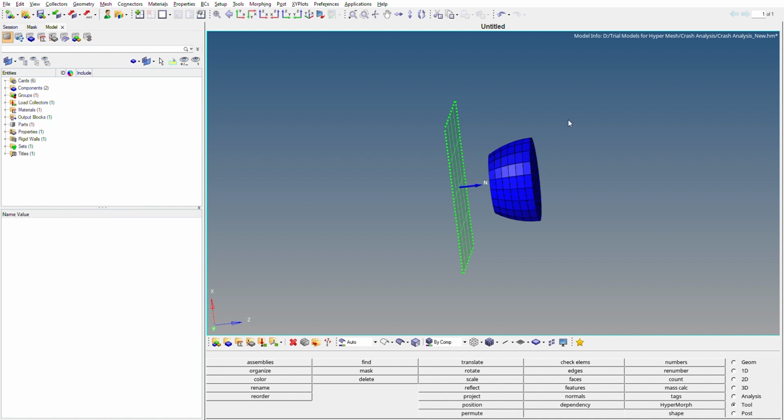Now all these are done from the model point of view. Fine. So can we proceed? Before proceeding, we just need to do some extra things, right? So what happens in Radioss as a solver, when the Radioss engine runs, you have to give some values as to how long the engine will run, like at what duration it will take the outputs, the results, at what frequency it will take the output or results. Okay, so for that we need to define these cards. For defining those cards, I've already defined these cards here.